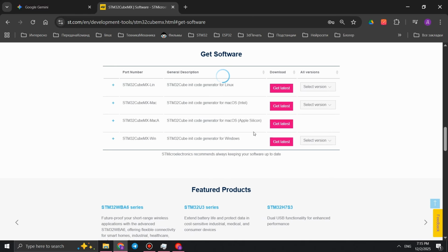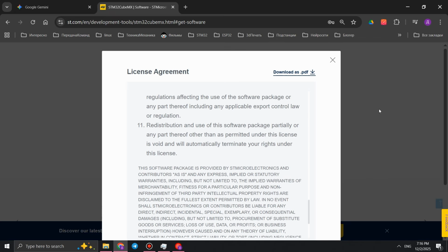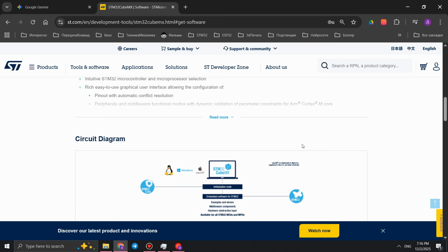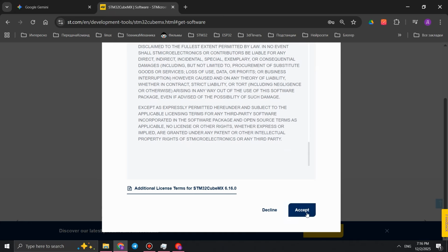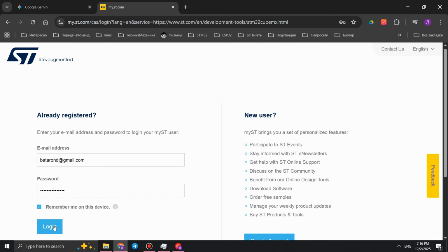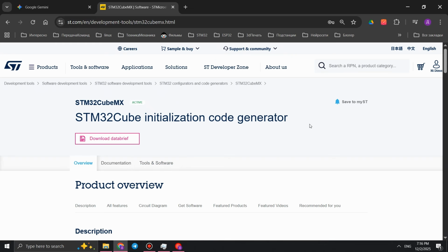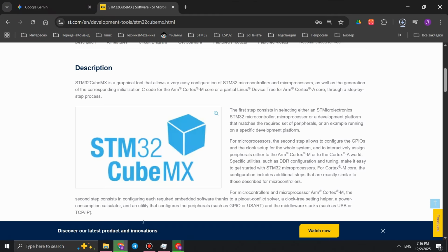This environment has no limitations and includes a built-in debugger and a database of many ST microcontrollers. But be careful, it only supports original microcontrollers, although it's possible to disable the chip ID check. I found a great seller of inexpensive development boards with original microcontrollers.